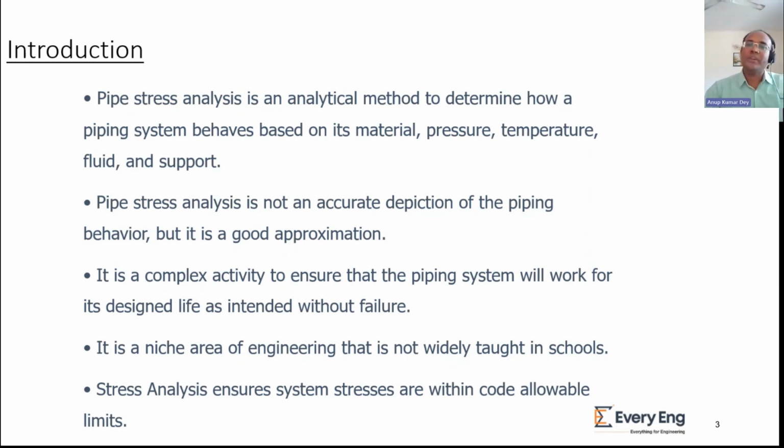For temperature, we have to provide a minimum of three temperature cases. One is maximum design temperature, then maximum operating temperature, and third is minimum design temperature. And there may be various other temperature cases also. For example, consider a two pump scenario, where two pumps form a header and then transfer fluid to some other place. In that case, it may happen that due to maintenance, one pump is not working and the other pump is working. So one pump working, the other pump on standby.